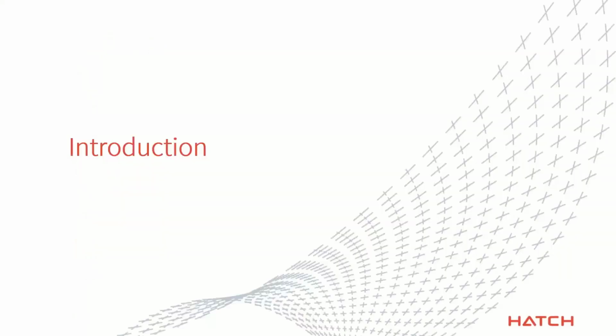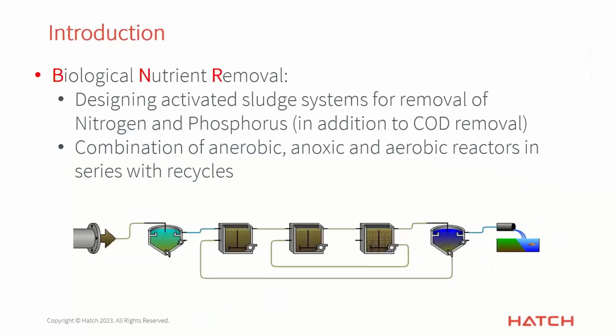Okay, so on to talking about BNR. Just for clarity, I'm talking about biological nutrient removal. So basically designing activated sludge systems for the removal of nitrogen and phosphorus. And of course, some COD will go along with that as well.